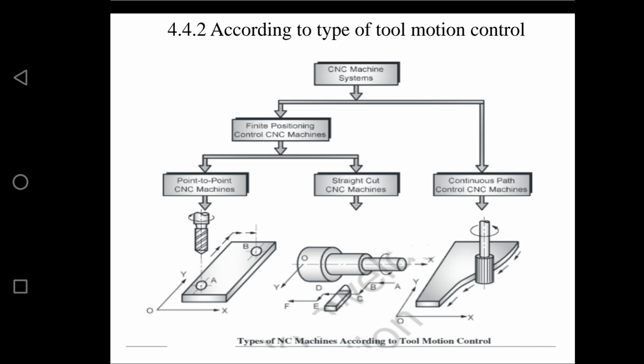Okay, the only important part is one position and another predefined position. If I have an NC machine and I program it to go from one position to another, where the path it follows doesn't matter, then it is called a point to point CNC machine. Examples are NC drilling machines, punching machines, or spot welding machines. Also, this type of control mode is the least expensive of all the modes. It is simple: just one position and the final position.